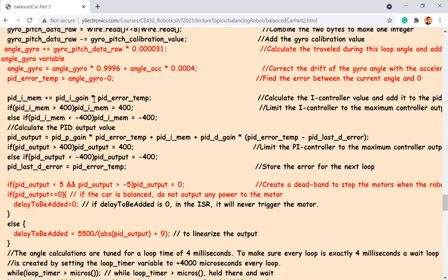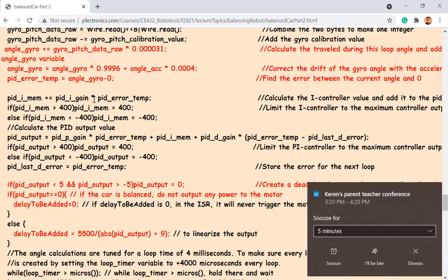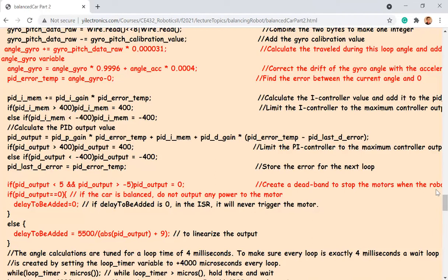And you are thinking, hey, if you keep adding the errors, isn't it a positive control? You're just getting more errors? What's the trick here? When it overshoots, you're getting a negative error, so it's still adjusting your PID output toward the set point. You are not having the errors in one direction all the time, right? Sometimes it's going to overshoot, so you are getting a negative error, so it's going to bring it back. All the P, I and D are trying to control it. When it's getting closer and closer to the set point, it's going to overshoot and then bring it back more efficiently. It's not like a linear adjustment, it's not just directly adding.